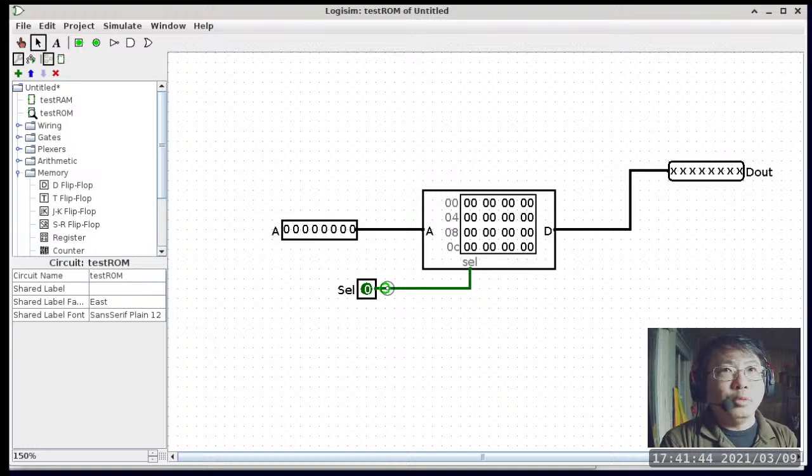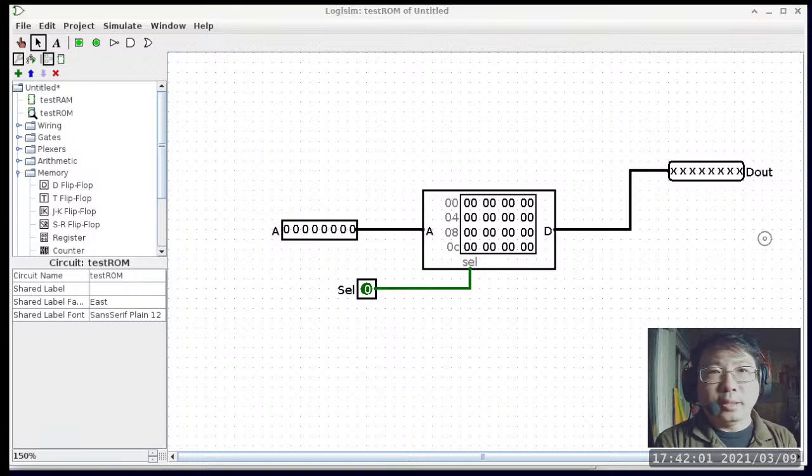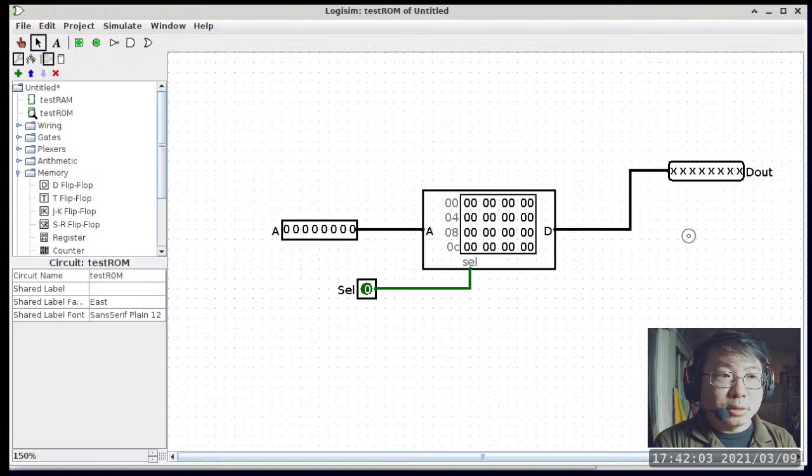And that way we can, because, okay, in the early days ROMs could only have like 16 kilobytes of data, which is not a whole lot, right? I mean, obviously by today's standard that is not much. So one single ROM usually cannot supply the content required by a computer. So a computer typically has a whole bunch of ROM chips in order to cover the entire address space where the ROM content is needed.